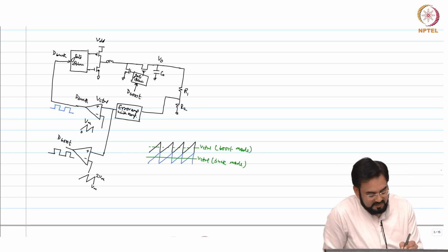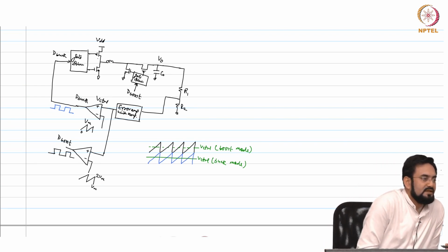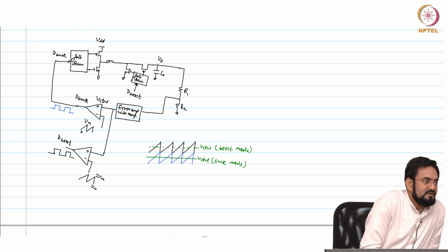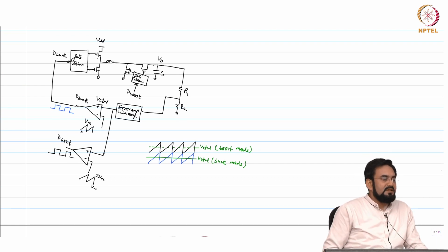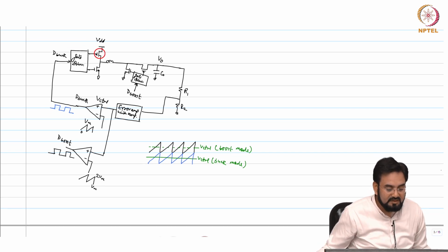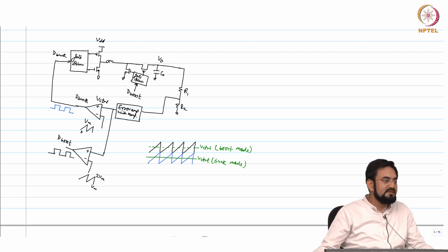Okay. So when your V control goes to VM, that high side switch in case of buck will automatically be fully on. We already know what was the logic. When you operate in boost, you want this switch to be turned on, this guy, okay, and this turned off. So 100% duty cycle means this will be on, this will be off, and then these two switches will start operating.